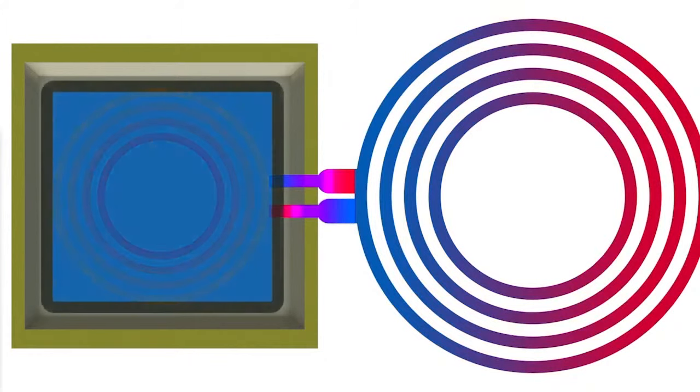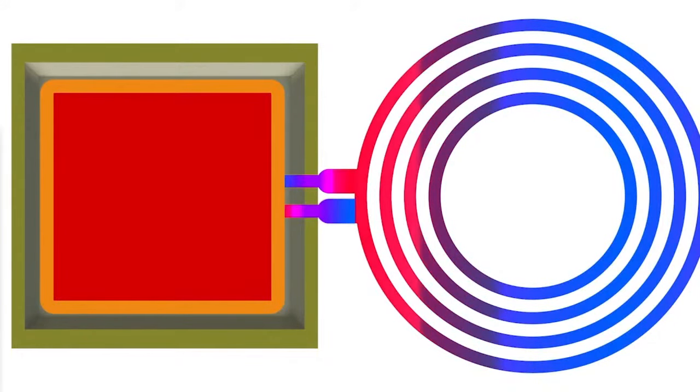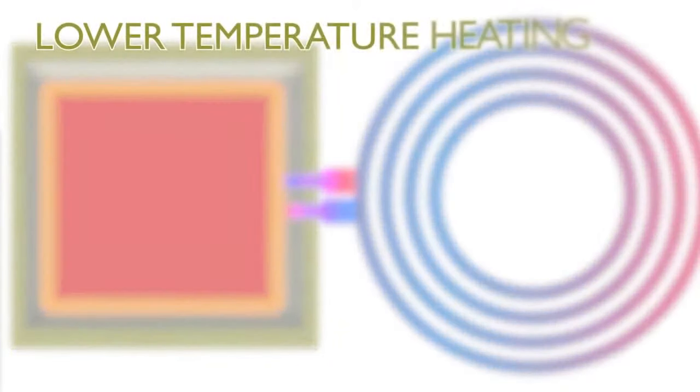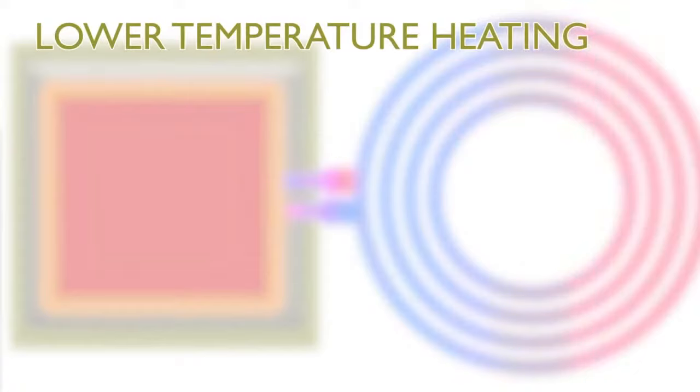Both of these systems commonly use a large water tank to act as a heat store, using the thermal mass of the water to retain heat energy until it is required by the heating and hot water systems within the house. Ensuring this heat store is well insulated is a critical part of ensuring these systems operate efficiently, and we have supplied the Spacetherm Air insulation in blanket form for use in insulating a huge variety of tanks and vessels. Both ground and air-sourced heat pumps are designed to operate at lower temperatures than fossil fuel or electric heating systems, and this lower operating temperature works particularly well with underfloor heating systems.